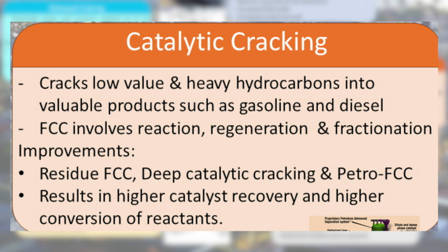The catalytic cracking process involves three basic functions. First, reaction, where the feedstock reacts with the catalyst and cracks into different hydrocarbons. Second is regeneration, where the catalyst is reactivated. And lastly is fractionation, where the cracked hydrocarbon stream is separated.